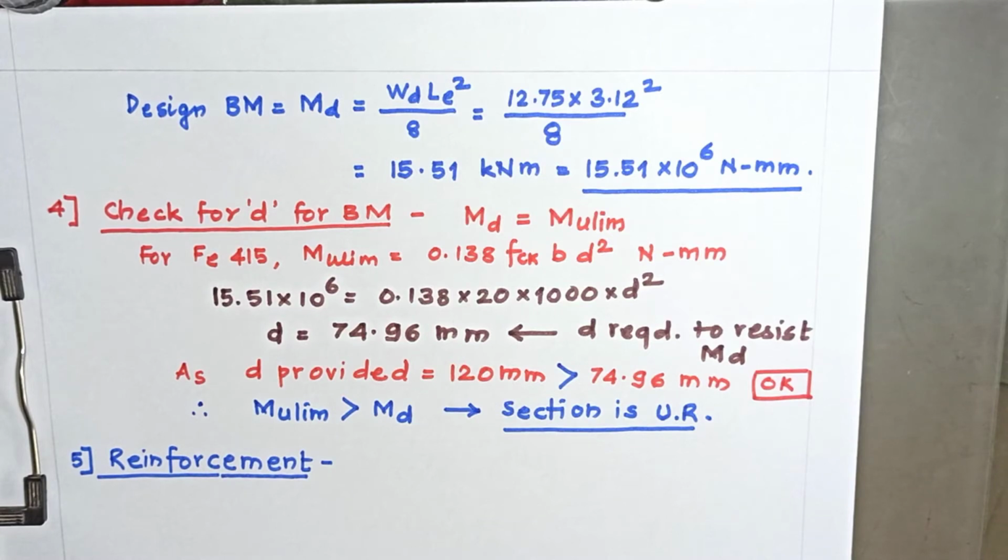Therefore, along the shorter direction, the reinforcement bars are laid first, that are known as main bars, and over those main bars, the distribution bars to resist the thermal stresses and stresses due to creep and shrinkage are provided, which are known as distribution bars or distribution reinforcement or distribution steel. Okay, so let us first go for main steel. Main reinforcement.